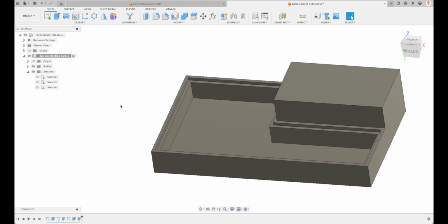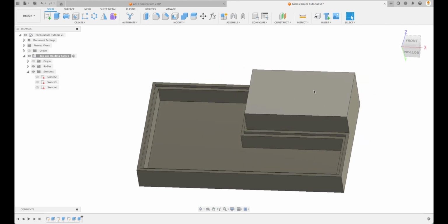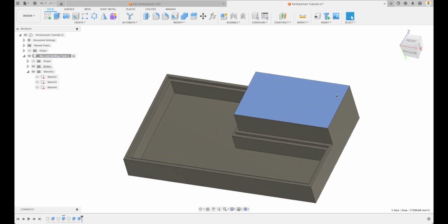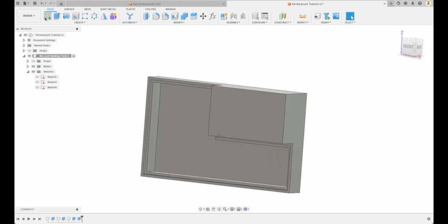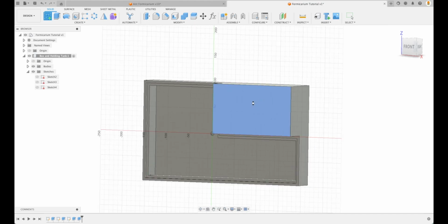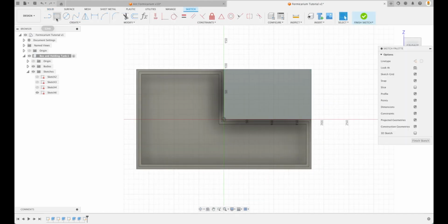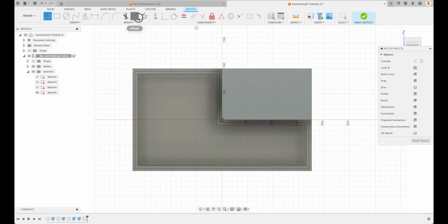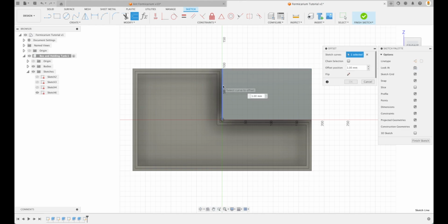Anyways, now that we've got this, we can now do the same thing to our holding box. So we're going to create another sketch there. Let's just create it on that face. And here we can't do an offset because that's going to offset all of those different edges. So let's turn off our chain selection in order to use this. And we're going to pick 1, 2, 3. Let's bring this over, minus wall thickness.